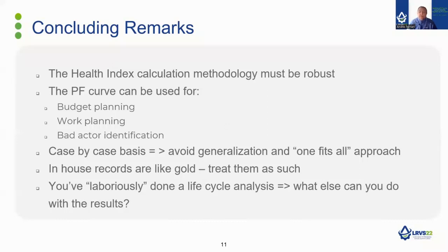I would recommend doing a PF curve for as many different repairable assets as possible, rather than having a one-fit-all approach. Obviously, that means more studies and more maintenance records at our disposal.